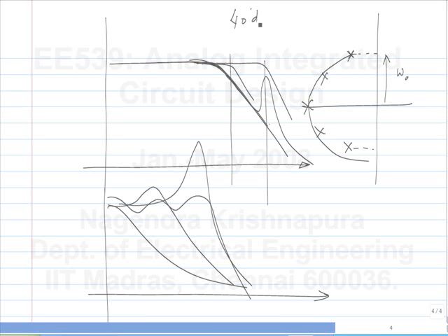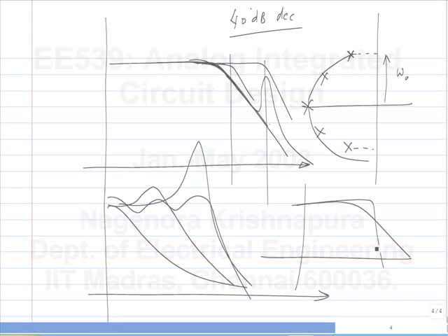So if you had, let's say, 6 poles and then you adjusted for maximal flatness, you would get a lot higher sharpness, meaning instead of this, you will get this. Is this the sharpness you are talking about? The sharpness of the attenuation? Yeah. So that depends on the number of poles. Okay. So with 2 poles, if you try to increase the Q, it is going to give you a peaking in the frequency response. That we decide is not useful for an amplifier. Okay.